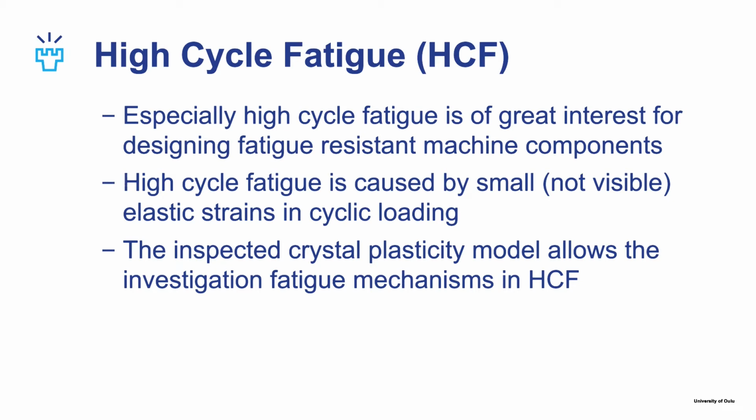High cycle fatigue is especially interesting for us, as understanding it is necessary for designing fatigue resistant components and machine parts, as those machine parts usually fail in the high cycle fatigue region. High cycle fatigue is caused by small, not visible elastic strains in the cyclic loading.